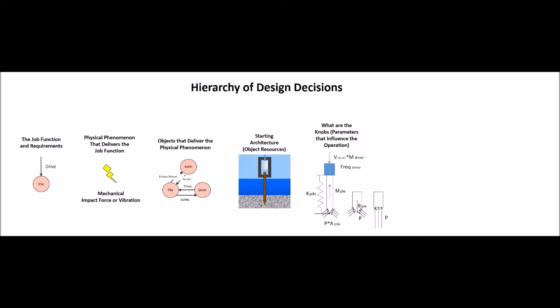The frequency of striking the pile will also determine the overall speed of driving. The faster that we recover the hammer and hit the pile again, the faster it goes in. It is also possible to time the striking of the pile, if it is done fast enough, to make the pile resonate, thus growing in energy and driving speed.